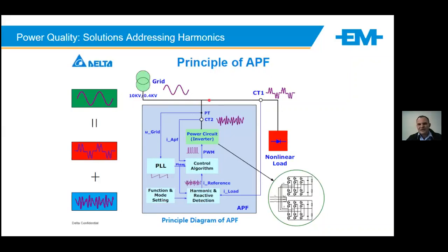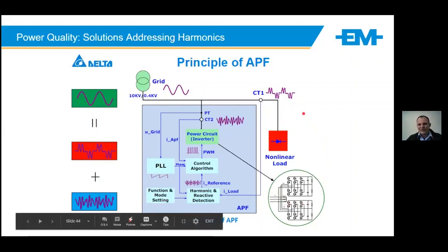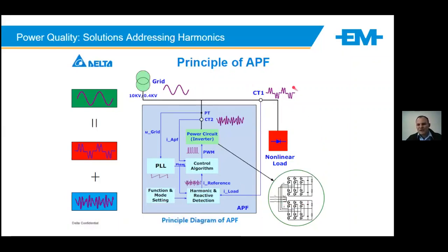All right. So if you were to measure at this point, that is what your waveform should look like versus that. So in this example, you can imagine if I had a whole lot of variable speed drives or whatever the case be, nonlinear loads, creating this harmonic profile, and I had other appliances connected here, I would optimally get as close as possible to this to give maximum benefit on any other appliance that may be wired onto that system.